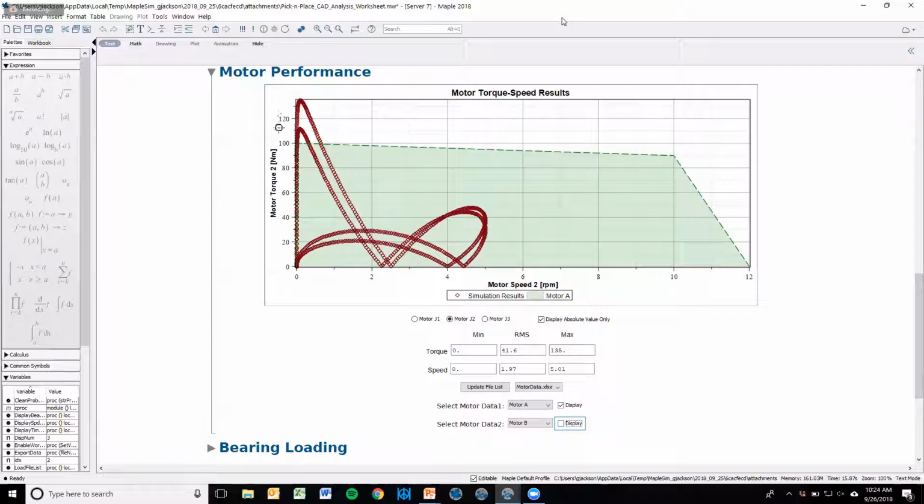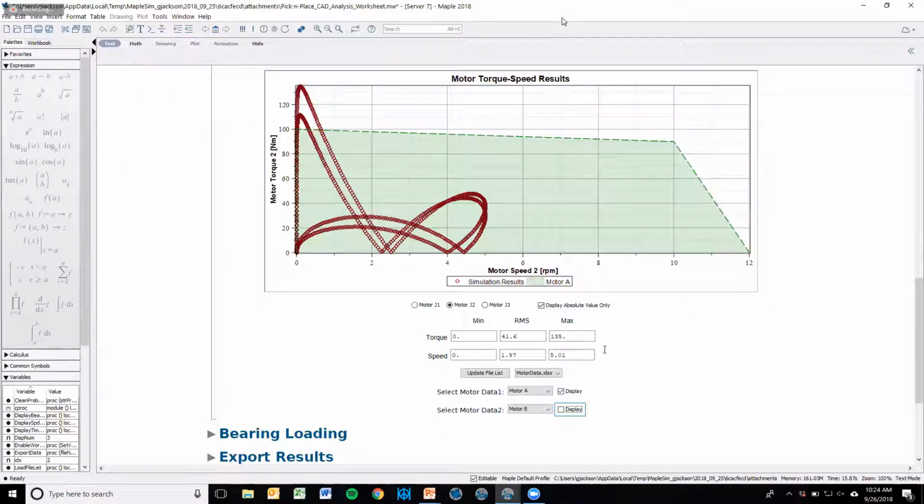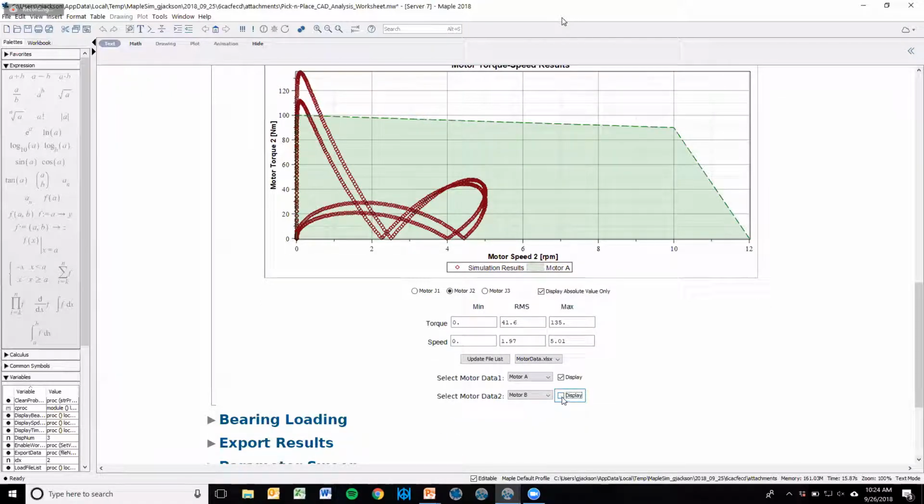And this is a kind of effect that a lot of other simpler calculation methods miss. If you're using spreadsheet tools and you're trying your best to calculate effective inertias, you might have to make a lot of approximations to really get at a usable number. And it's just hard to know how valid those assumptions are sometimes. So we don't need to make those in our software, and we can be very confident that motor A is probably not going to do the job how we want.